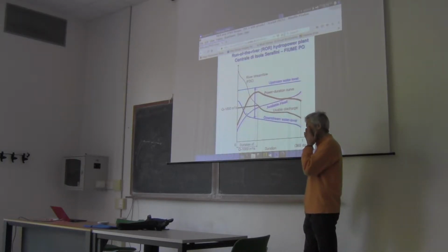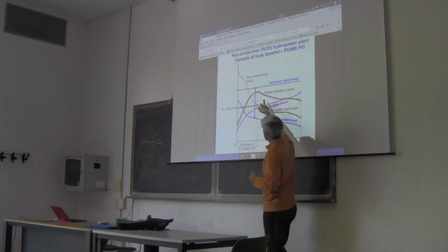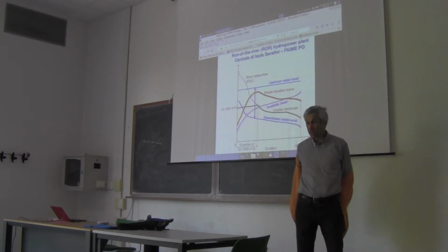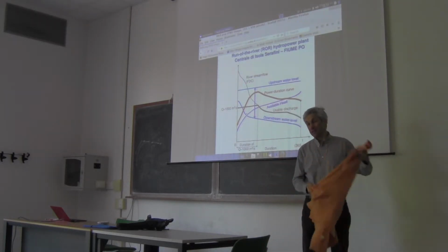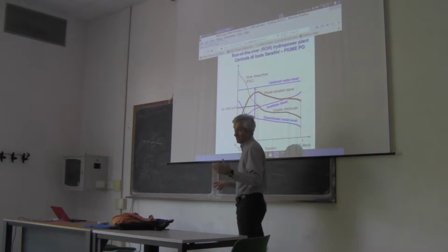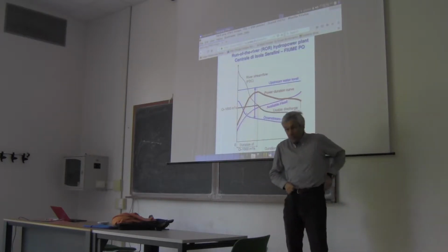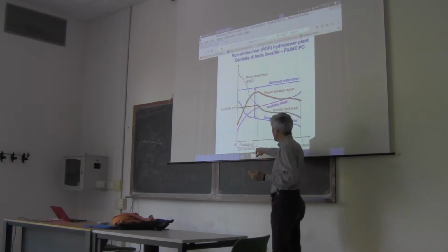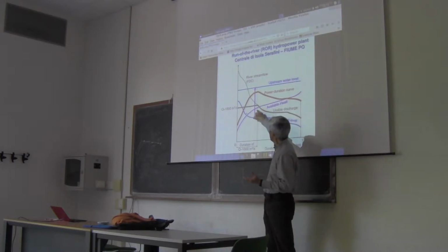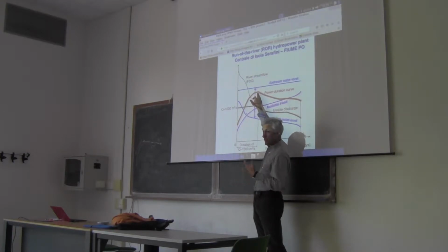Okay? Now what's interesting is to see the power duration curve. As I said, this terminology is a bit misleading, because actually it's not a duration curve. It's a curve that shows the power depending on the river flow. If we refer to a river flow with a duration that corresponds to 1000 cubic meters per second, this river flow corresponds to the highest power.